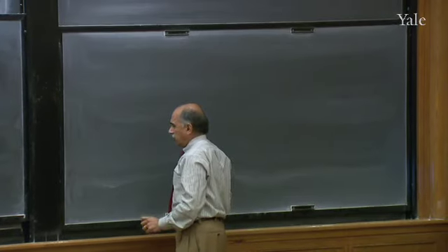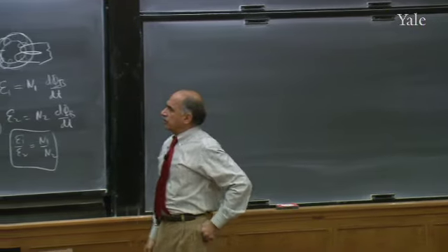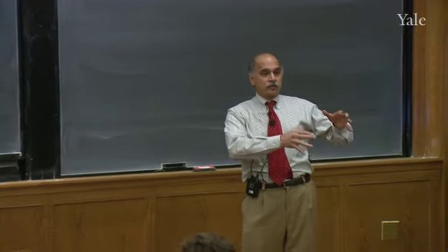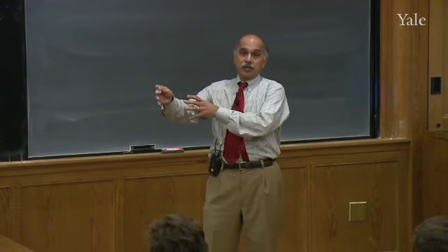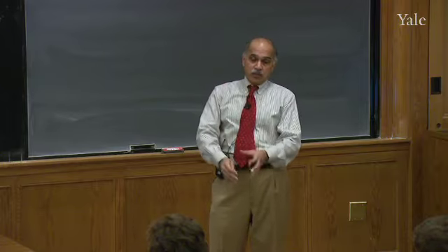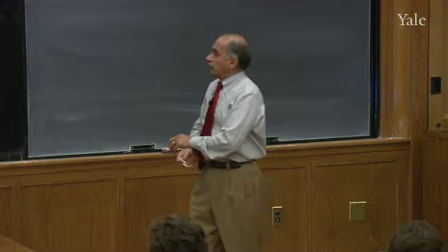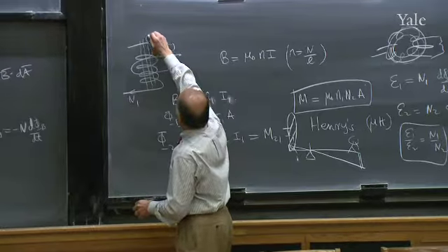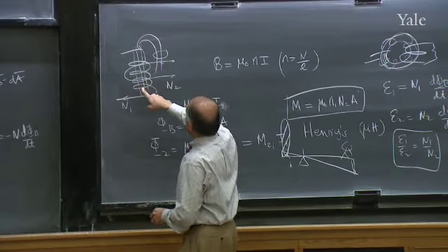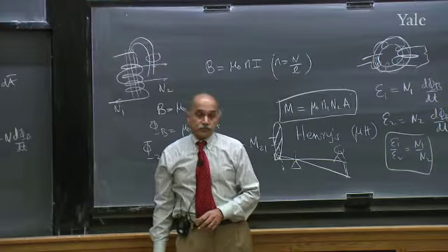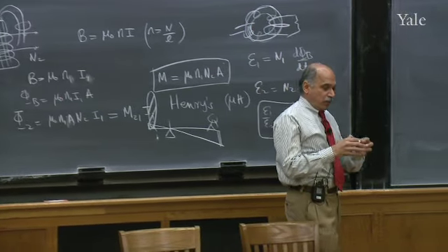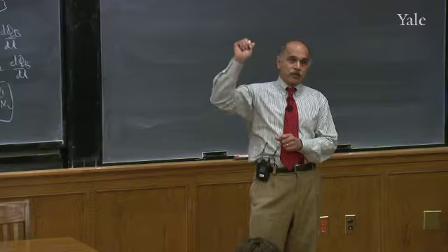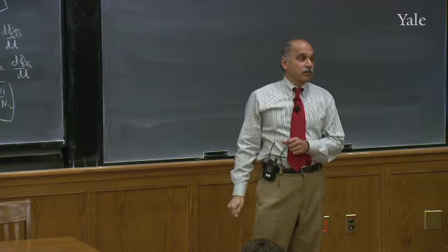Okay, now we are going to come to something that is really a curiosity. I'm not going to use it very much: the notion of mutual inductance. Mutual inductance is one coil trying to generate a voltage in a second coil because they share a flux. When it's changing in one of them, it's also changing in the other one. They don't have to be coaxial. You can put a second loop way over here, and maybe some extra flux coming out is penetrating this. There's a mutual inductance between this guy and that guy also. Anytime the flux of one coil can go through another one, you have a mutual inductance, because if you change the current in the first coil, you're going to generate a voltage in the second coil. That's why you need to know that proportionality.